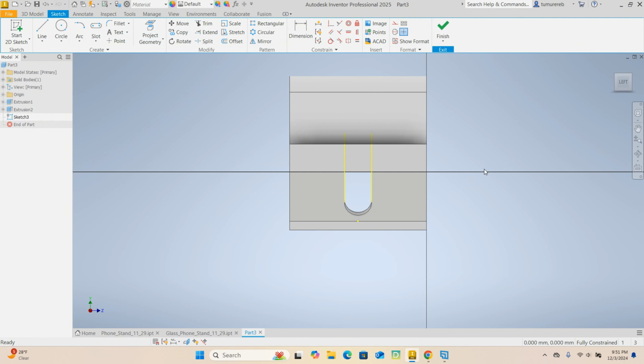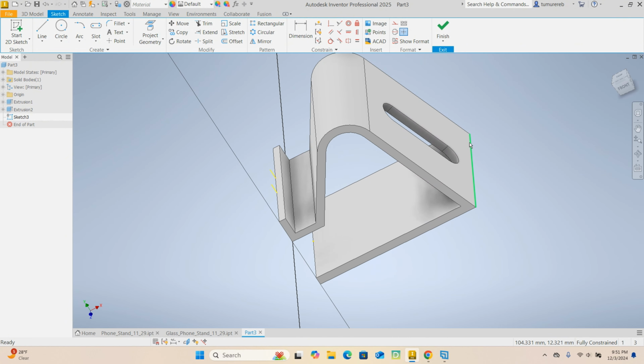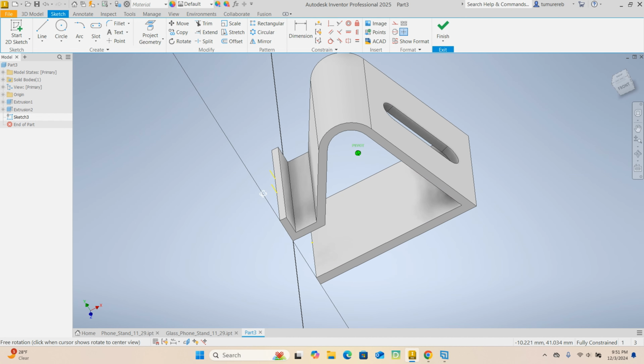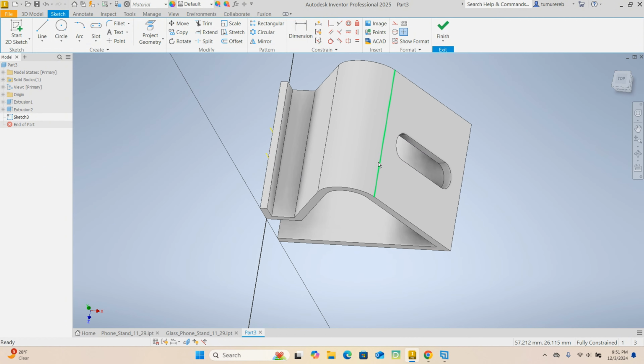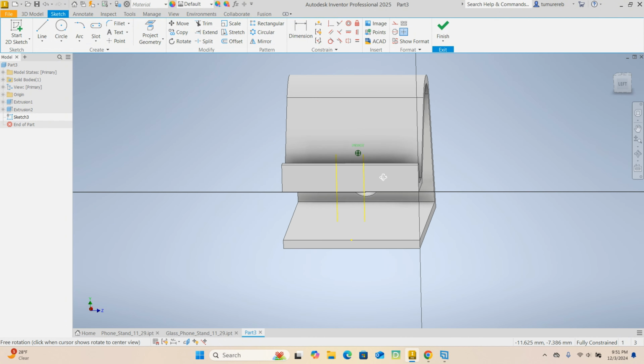And the reason why I'm doing that is so that if you decide to use this as a charging port, it aligns. Your charging port comes through here and aligns there. So project geometry is going to make sure that's the same distance. The fastest way to do it. I'm also going to project these lines there. There you go.